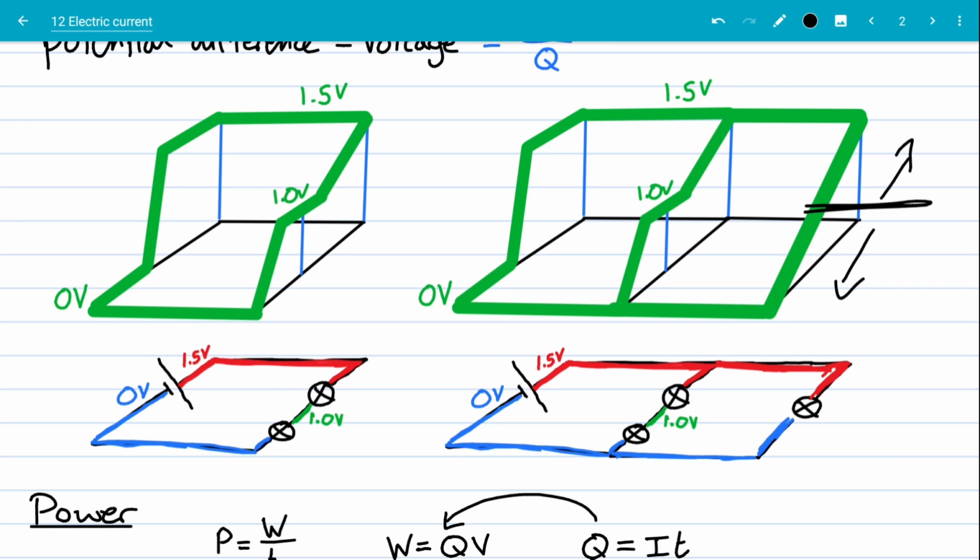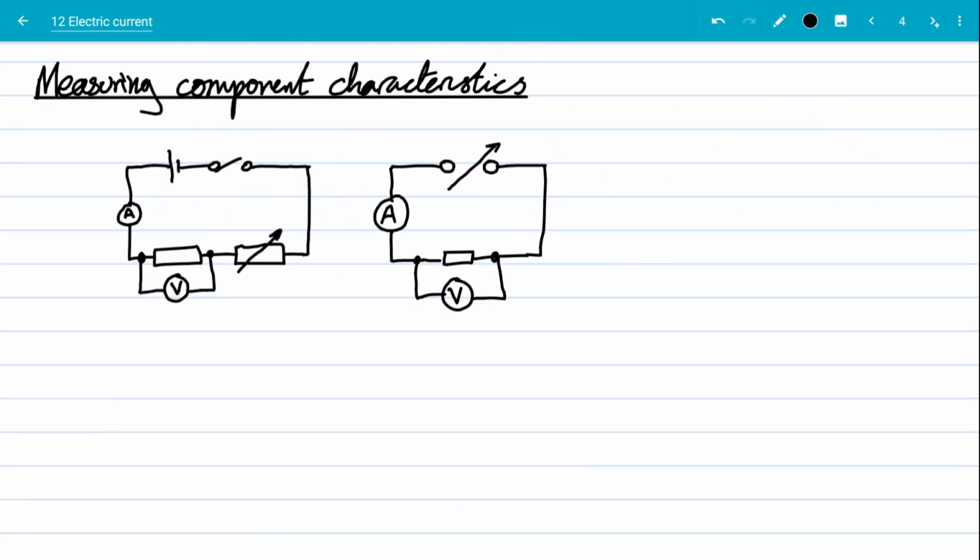and down here. And the higher up it is, the more of the 1.5 volts potential difference there is between that and the ground. And the lower it is, the lower it is. So that is what we do with this potentiometer. We connect one side to there, and then the bit in the middle slides up and down, so we can select how much of that 1.5 volts we want. Again, having that potential model in our head is a better way of going.